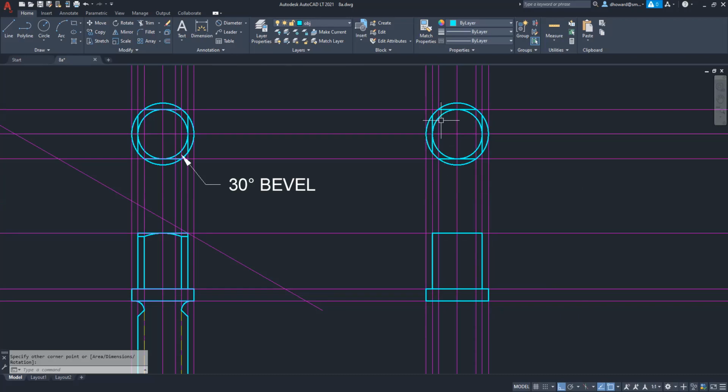So we've got the corner issue taken care of in the top view. Now we need to address it in this side view here. You can see that this construction line, which I referred to already, to show the root of the thread, just happens to line up with where this face intersects that corner, right on the money. So you can just draw that line, and that is what it would look like. That's essentially a bevel, or a chamfer.